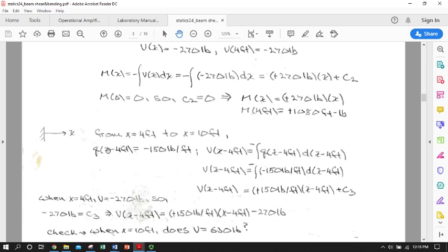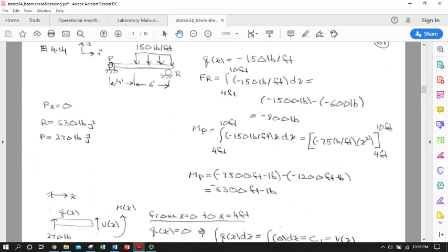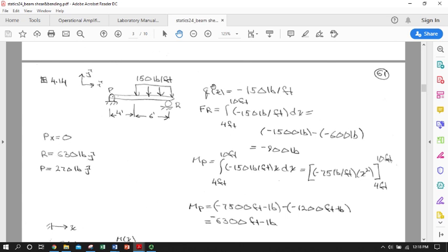Well, we know that our distributed load is going to be a factor. And because we've now indexed our coordinate system back here to the back end of the beam, we need to write an expression for q sub x that's referenced back here. So our original expression really was kind of faking it.